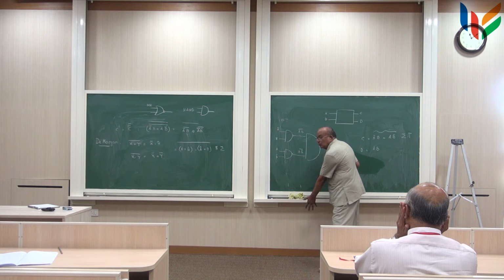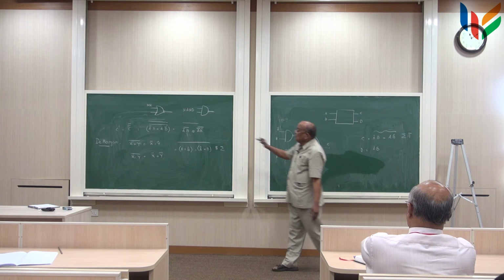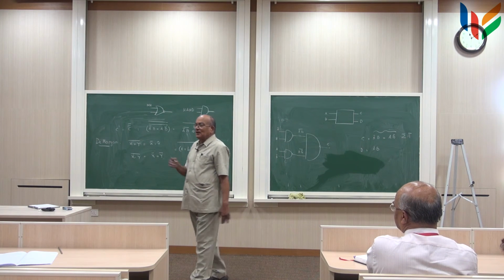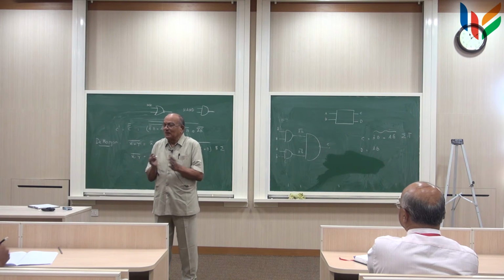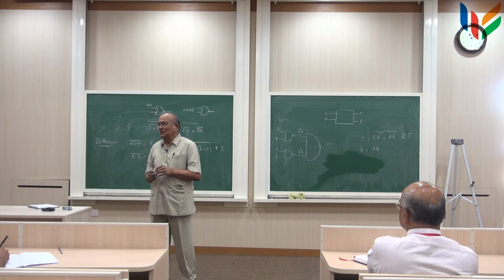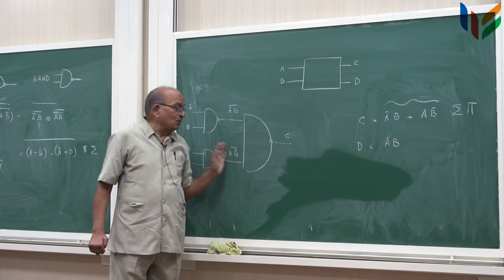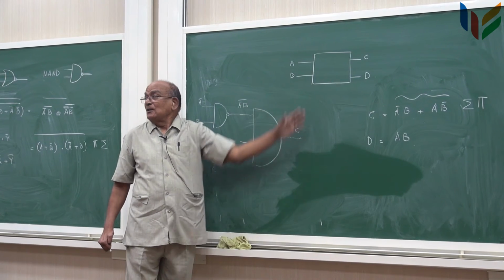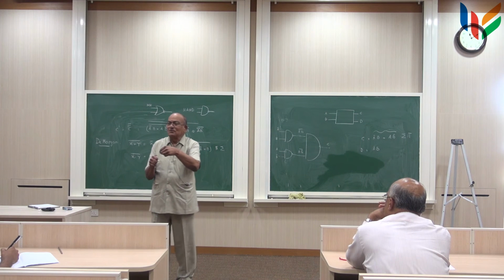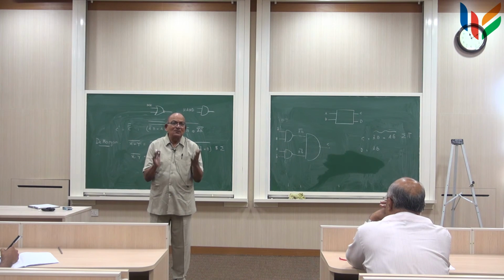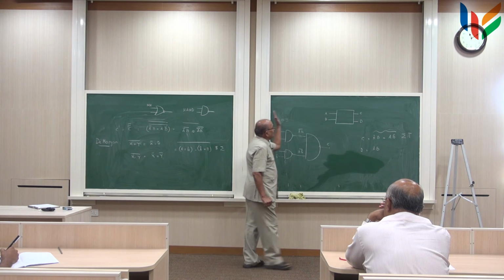must be ANDed with another output coming from some other circuit here, right? And we are assuming them to be combinatorial logic. Strictly speaking, this is not a combinatorial logic because there is some amount of delay time. It becomes combinatorial logic only after the delay time. Now, it may turn out that if that one has a lot of gates in the line and this one has 2 gates in the line, that one will have a lot of delay, whereas this one has a lesser amount of delay. And when you are adding these two, you are adding wrong values of binary Boolean values, right? It's possible. So I must design circuits such that at each stage this is kind of balanced.